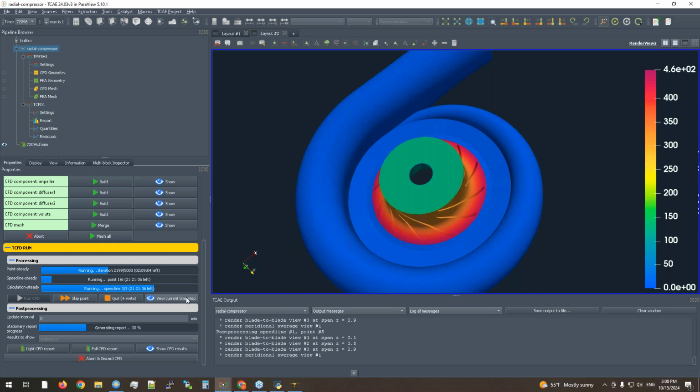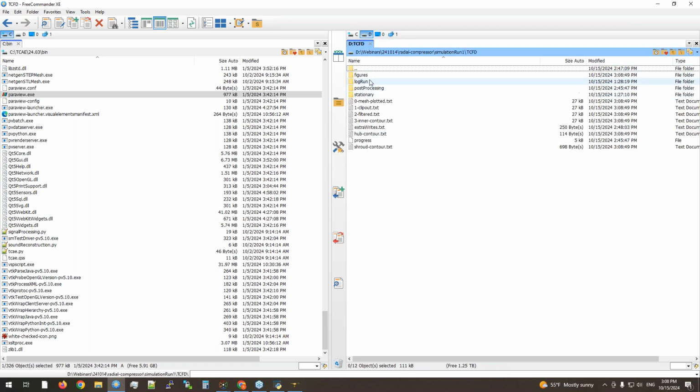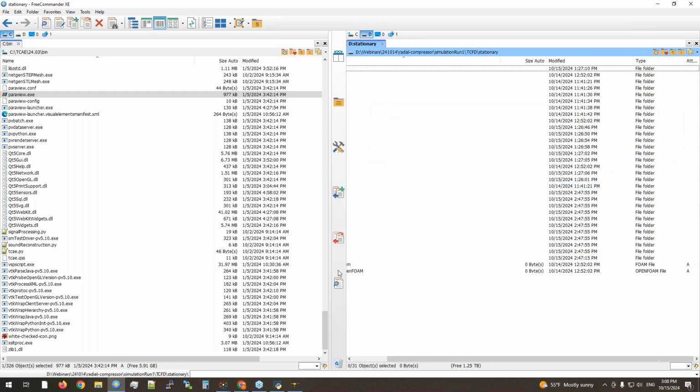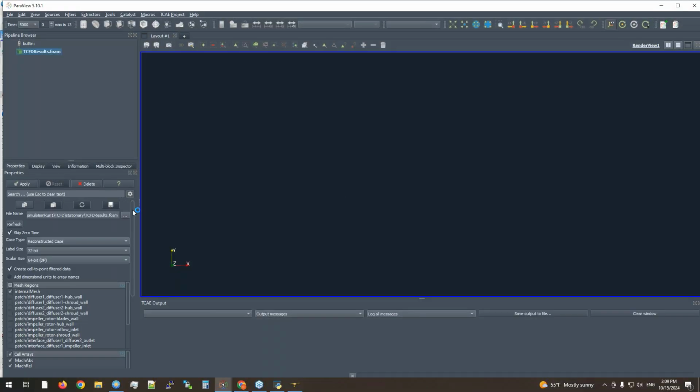The alternative to wall functions is a fully resolved mesh to the wall, where Y plus is on the order of just 1. The software is completely ready for that, and it's up to the user what mesh size and Y plus is used. It's relatively straightforward to set everything.